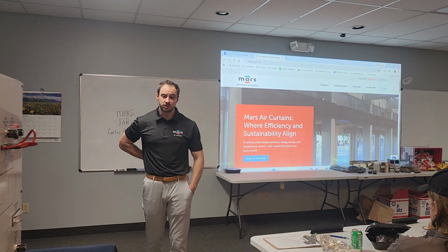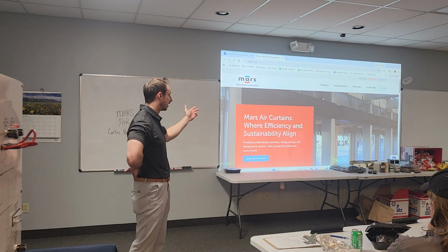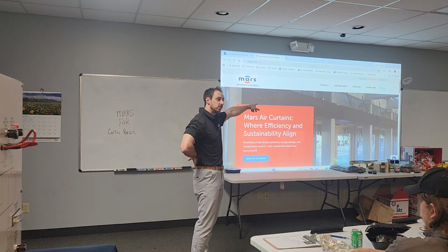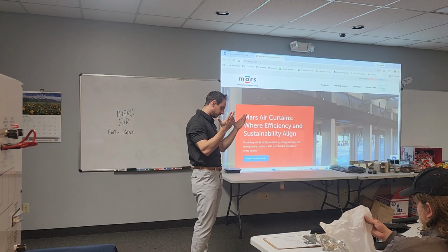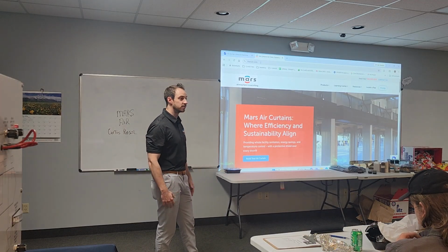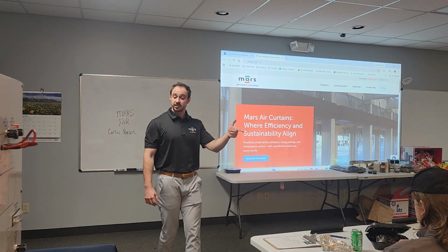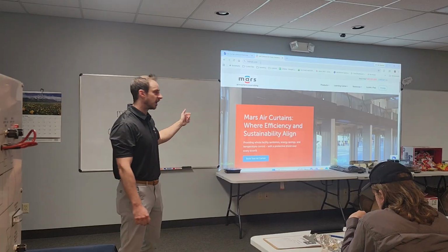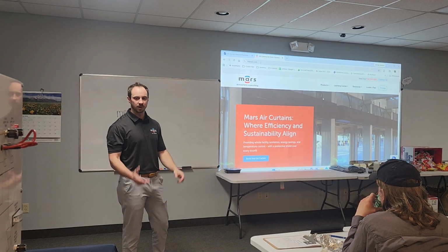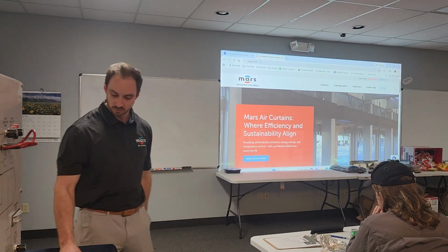Yeah, it's pretty straightforward. Obviously the larger units, you might have to get in a little more, but like the ones I've been showing you, the ones in the background there, it's really just taking off the intake screen, and then it's a dual shaft motor, so you just take off the wheels, and then reattach. That's it? Yeah. Okay, so that's pretty straightforward then. Yeah, that's a good question, and I think that's one of our videos as well. We break that down in a 2-minute video, how to swap the motor. So that shows it well on the YouTube channel too.